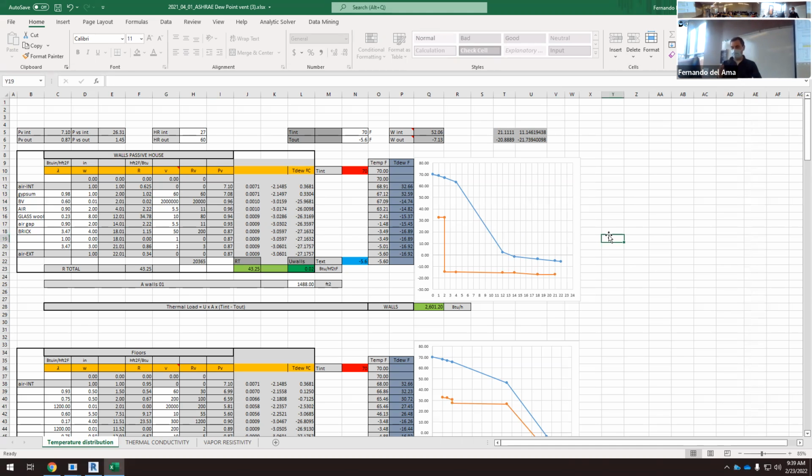Okay, so in terms of thermal resistance, the vapor barrier doesn't matter at all. So that's why in THERM, we're not simulating this, because in THERM, we're not calculating condensations. In THERM, we're just calculating the R value of a detail that has different materials or where there is a corner. So we're calculating this kind of R value. We're not calculating condensations. But here, if we run the first simulation without the vapor barrier, and we do have condensations, then we have to add it.